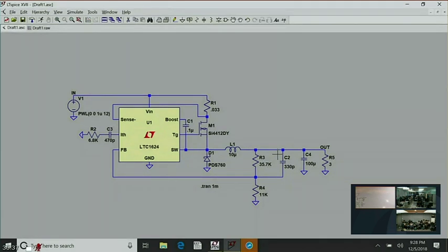One side of the short circuit to ground detector comparator is the feedback pin voltage, which is a divided version of the output, and the other side is a divided version of the reference. So this thing detects that the feedback pin voltage is too low by a factor of 3. If it is, then that fires the short circuit to ground detector and slows the switching frequency down by a factor of 100. Now, this might seem like a sloppy way of detecting short circuit to ground. Think about it. It looks at the feedback pin voltage. It says, oh, the feedback pin voltage is too low, say by a factor of 3.